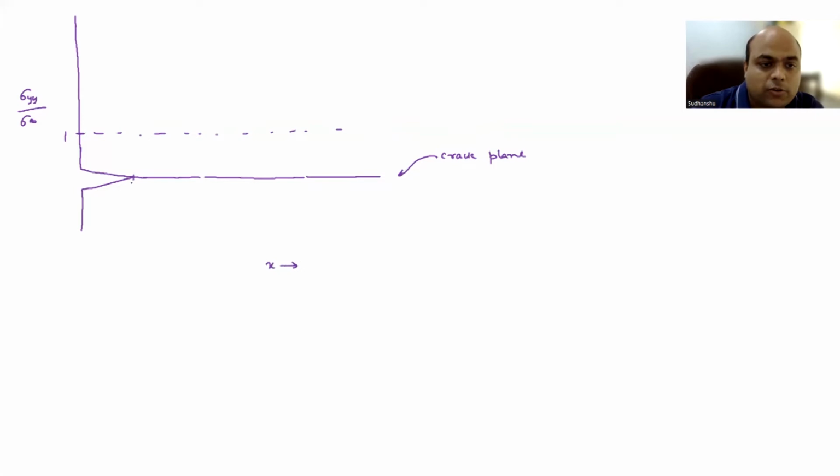So what is the value at the crack tip? x is going to be a, right? The half crack length, and r is equal to 0. Then we can put say 2a, then 3a, then 4a, and so on. It can continue like that. So if you see the table for Westergaard at the crack tip, it tends to infinity, right?